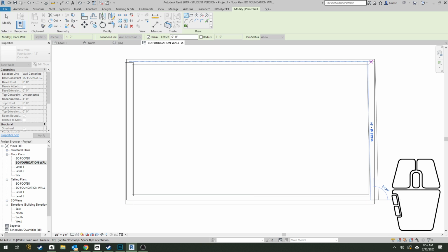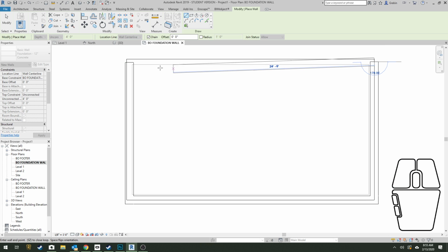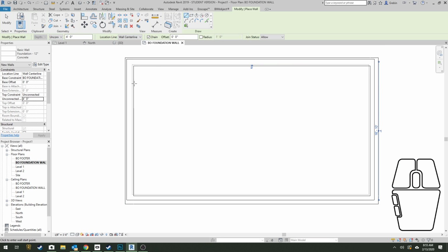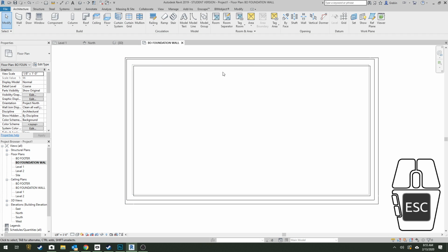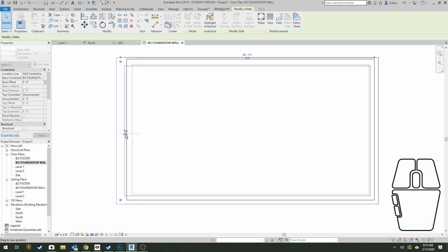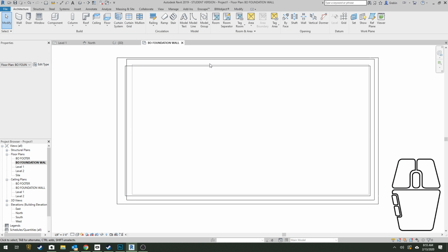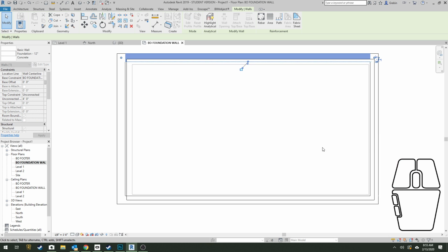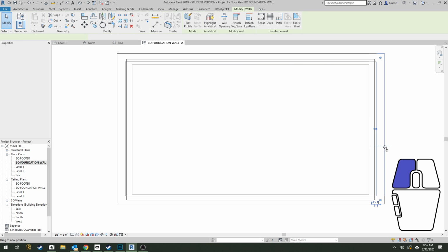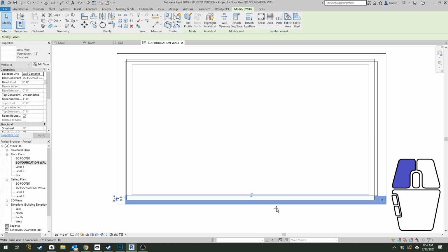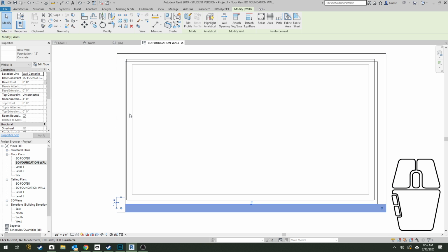Now, as you can see, it's not perfect at the moment because I'm having issues with the connections because I can't actually connect to those walls. What I do is I draw it roughly, and then I come in, because it's a little thicker than the walls that I have, and I'm going to use a tool I just showed to Ari yesterday. I want to make sure that all my walls are actually a little bit outside of my original walls of the house, so I can see my walls on my house. You see the walls of the house are here, foundation walls are out here.